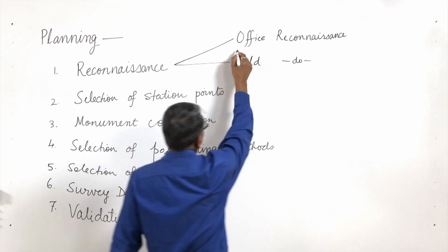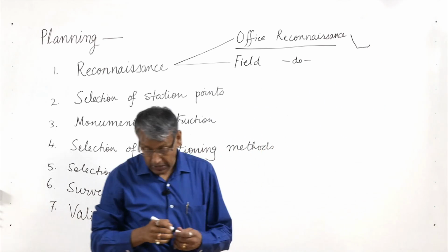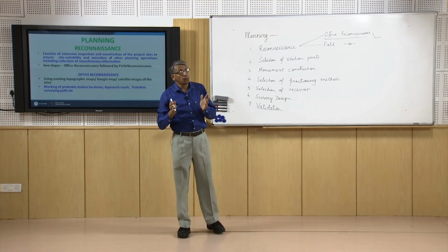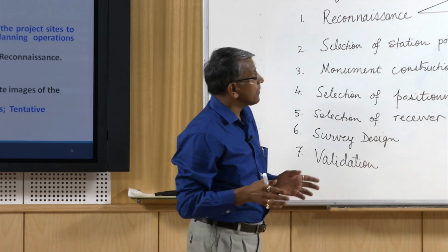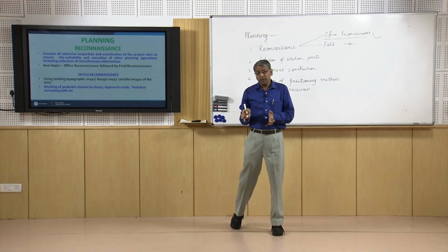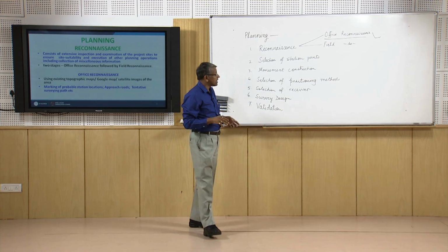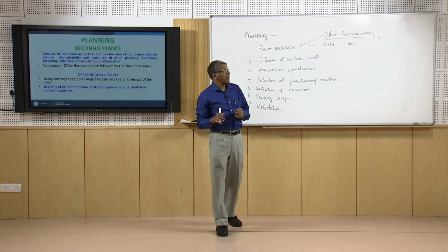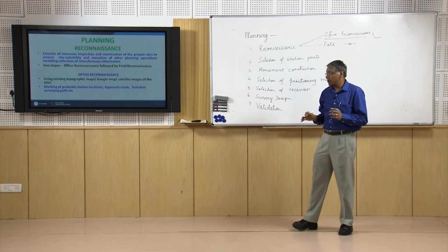Now, in case of office reconnaissance, we do it inside the office. We take the existing topographic maps, images, aerial photographs as large scale as possible, and in those existing maps and images we thoroughly look at the project area and whether the area is viable for GPS surveying or not.